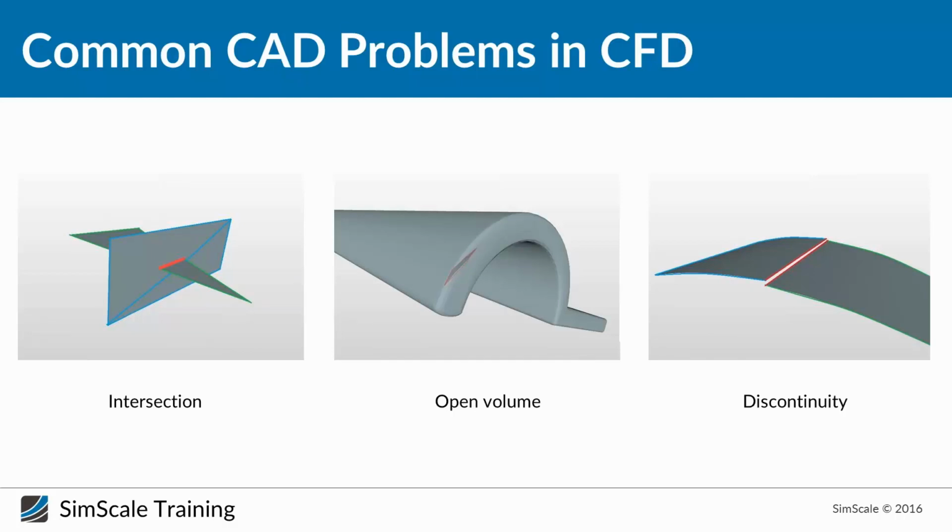But sometimes when you work in CAD, you will lose some edges to select, so you will have open surfaces or holes. Sometimes this can also happen when you do the conversion from a CAD software, or from the precise surface, to the tessellated surface.